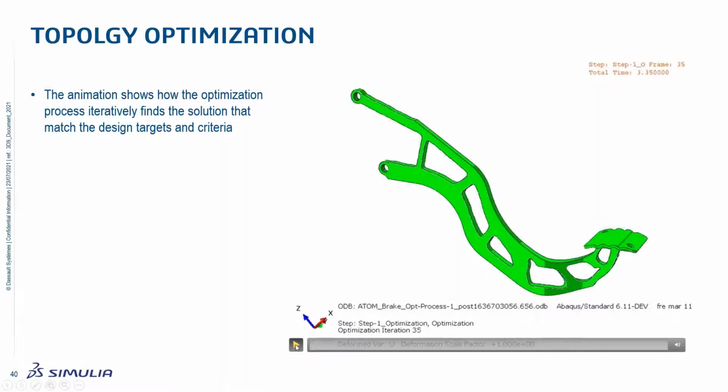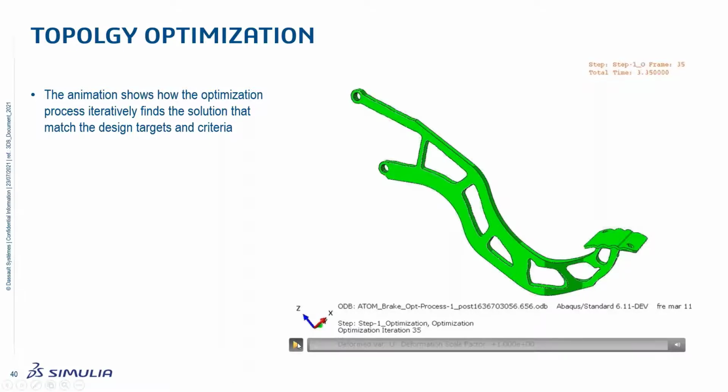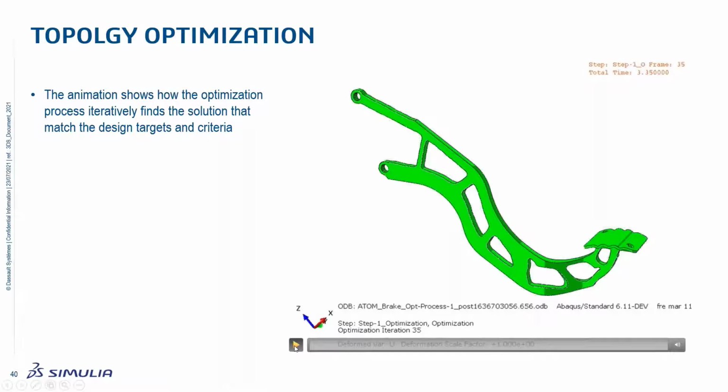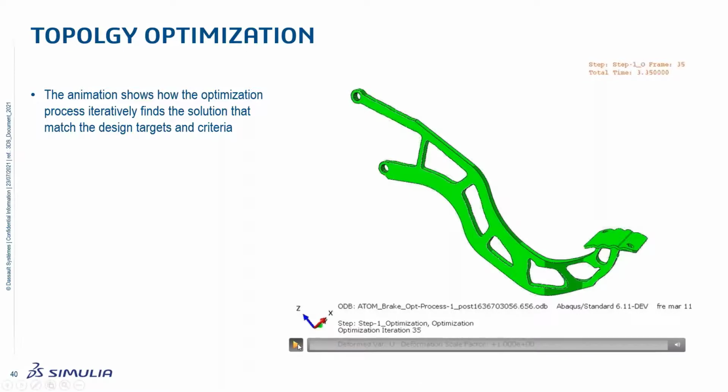The strategy is really to try to take out material with small stresses, which subsequently will raise the stresses in other regions that will be conformed to comply with the limitations, the constraint we have imposed.